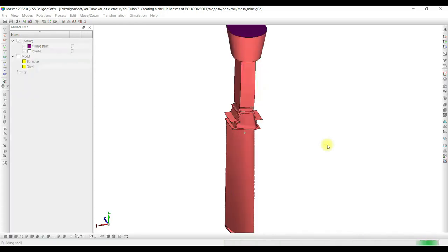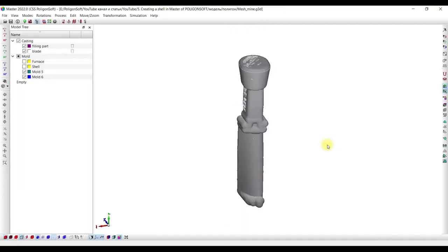The program is now making a copy of the volumetric mesh while removing the surface mesh. Next, the program checks the quality and cleans the bad elements, and then the model is sent to the Salome Mesh model to create a 3D mesh. The shell has been created.